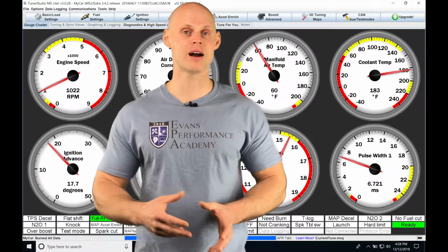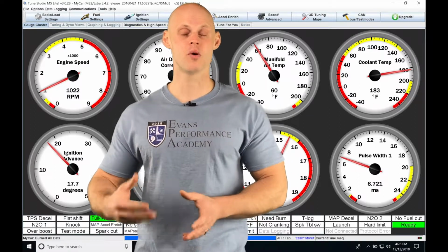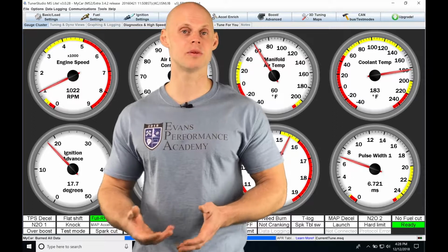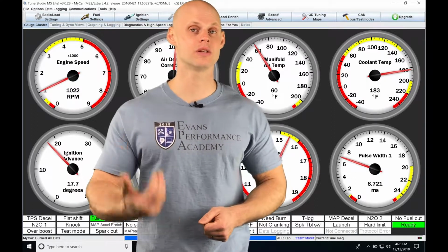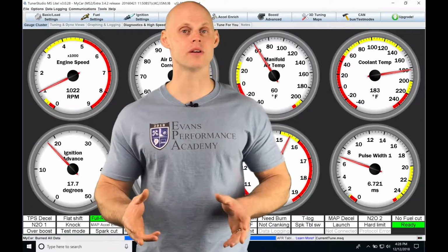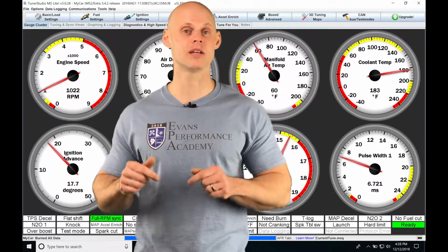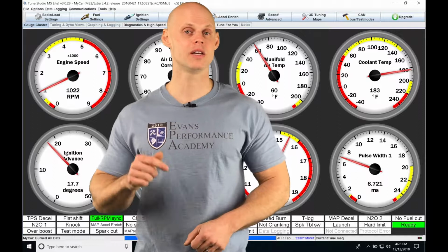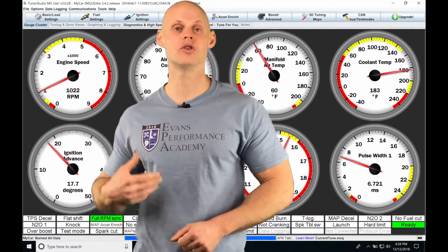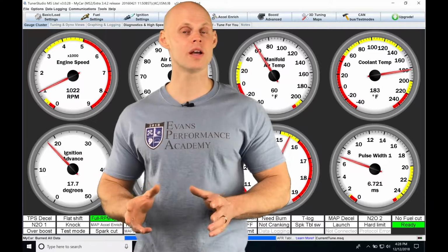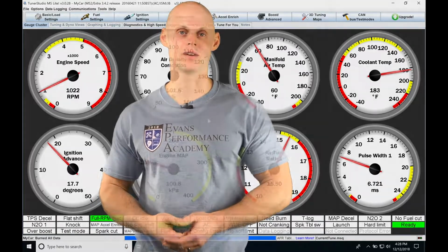We have to block out that kind of density or false reporting density coming in the ECU, because what's going to happen is we're going to go ahead and pull too much fuel out, and we're going to be finding that the engine starts to run lean. So in order to get around this, we have to use this biasing table we're going to be taking a look at in this video. We're going to be seeing it's very important to set up right. I'm going to be giving you some decent settings to go in and get your tuning started with. So without further wait, let's jump into the video so we can check this out.